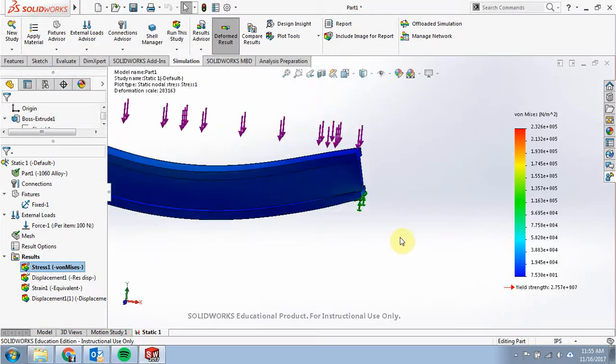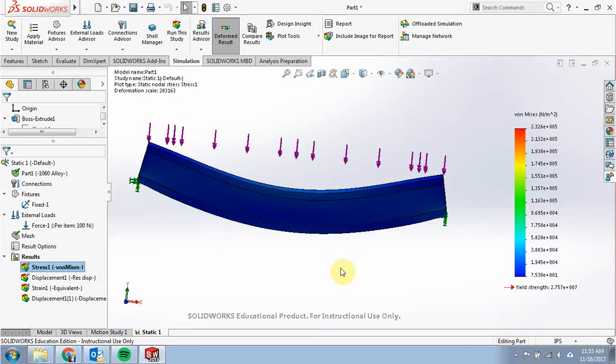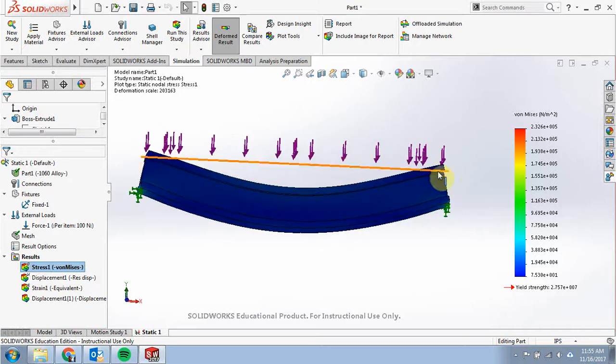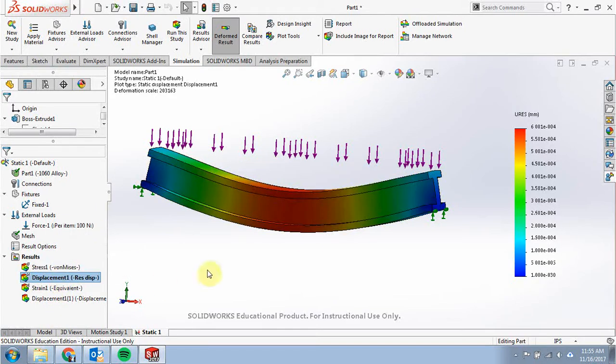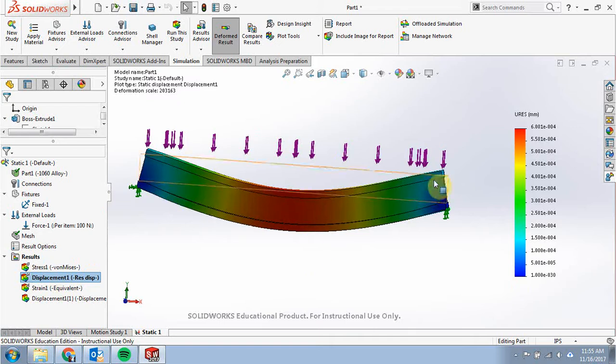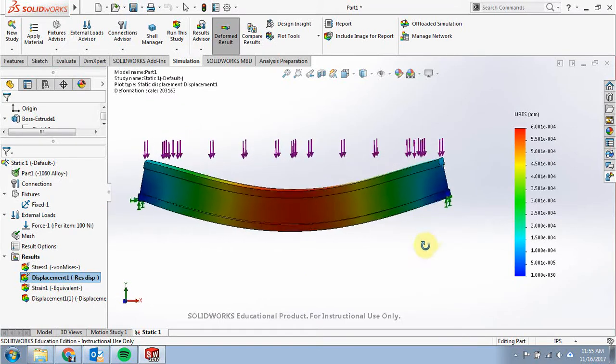Now if we take a look at this head on, you can also see that these tops are bending in. So that's why we're relieving some of the stress, and it's dispersed only on these bottom edges now. And again, if we show the displacement, you see that this gradient now extends all the way up into the top a little bit because it is free to move.